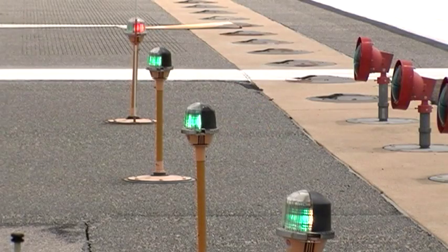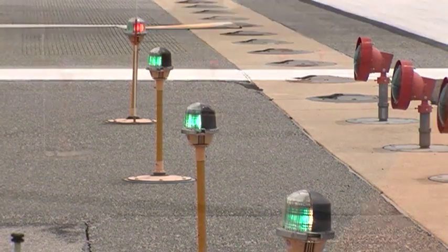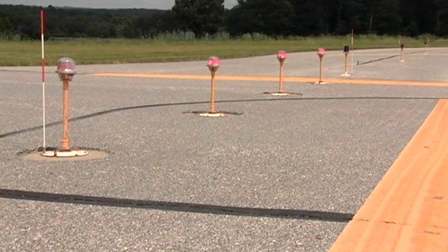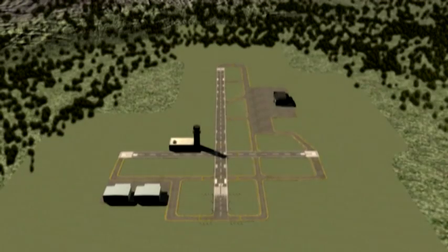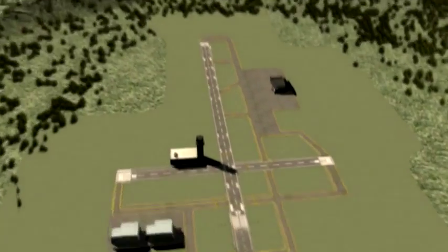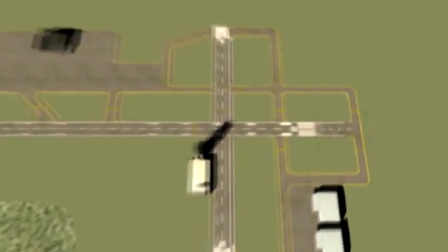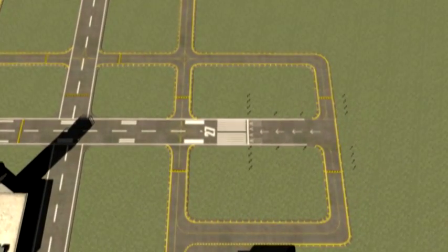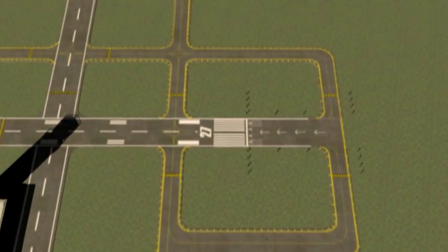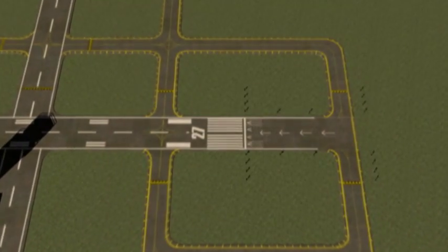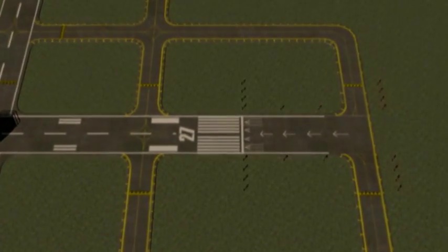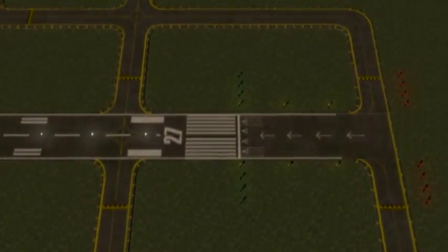When viewed from an approaching aircraft, threshold lights are green to indicate the beginning of the runway. But when viewed from the aircraft taking off in the opposite direction, threshold lights are red and taxiway edge lights are blue. Edge lighting for a displaced threshold is somewhat complicated since the area between the threshold and the pavement area is not considered to be usable runway for approaching aircraft, but it is considered to be runway for other operations. For this reason, it's necessary to use several split lenses.